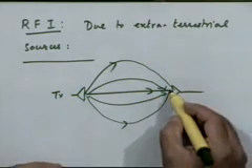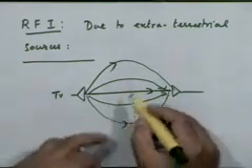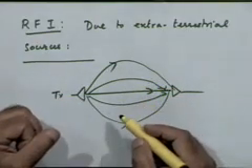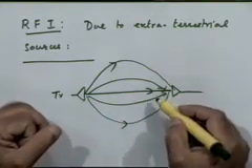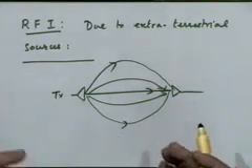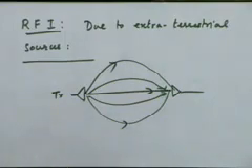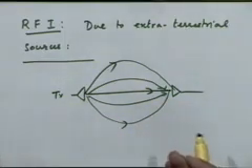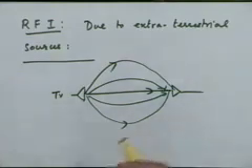What is more, depending on the relative delays of these paths, the signal here may be weak or strong. Suppose we take a sine wave, delay the different phases and add them. You are adding the same frequency sine wave with different phases, right? Depending on the relative phases of these various sine waves of the same frequency, the net amplitude of the resultant sine wave may be either small or large. They may reinforce each other, or they may create destructive interference for each other.